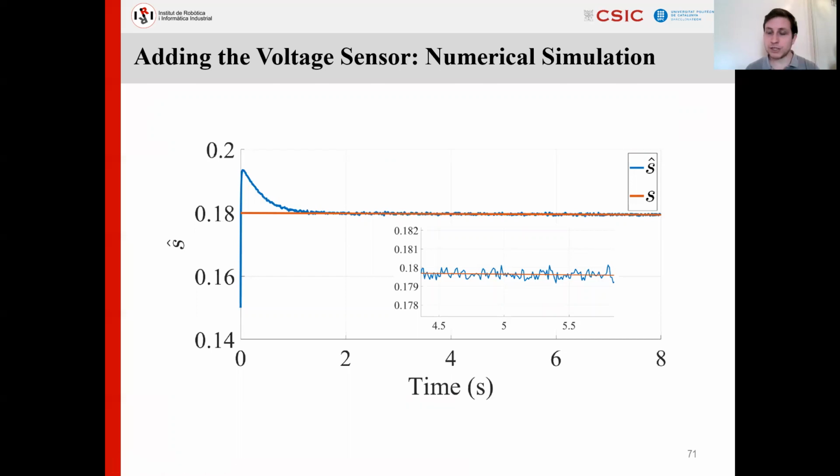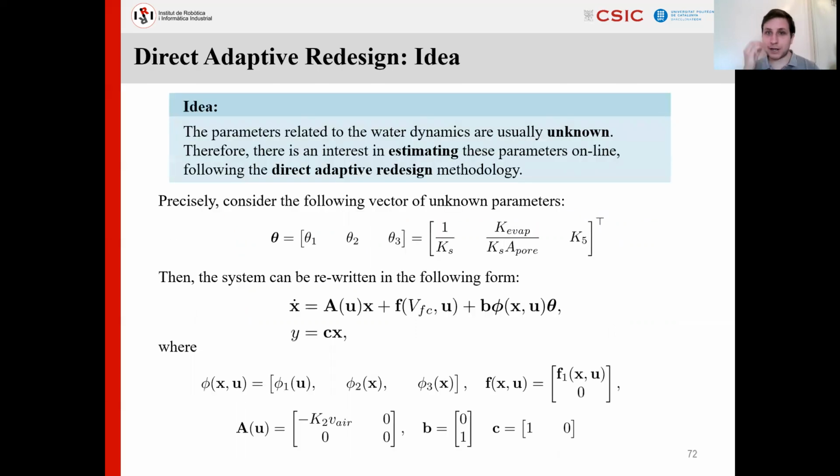Moreover, we see that the noise sensitivity of the algorithm is drastically reduced. Intuitively, we can deduce that this improvement appears because by exploiting the monotonic condition, the state estimation of the observer is pushed in the right direction during the transient. Therefore, we require less high-gain feedback terms, which drastically reduces the noise sensitivity of the algorithm. And finally, we proposed a last modification of the algorithm.